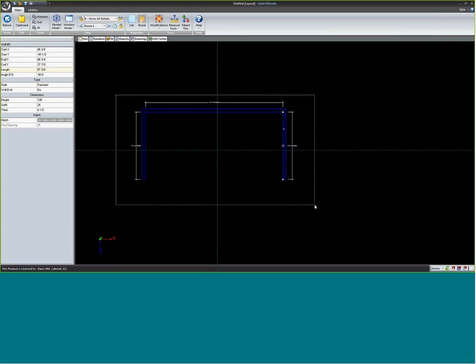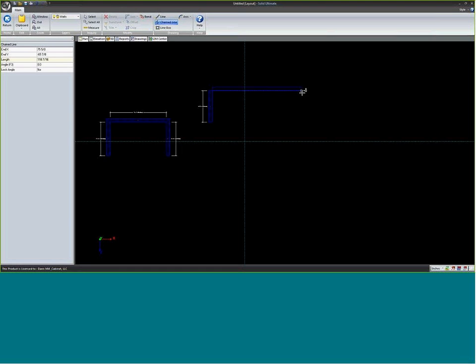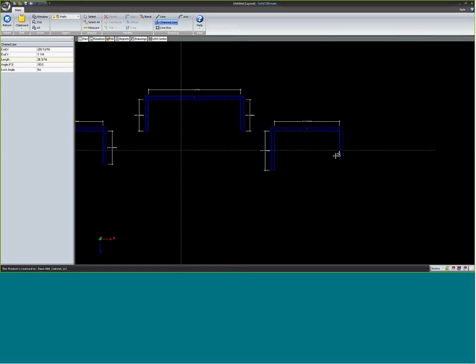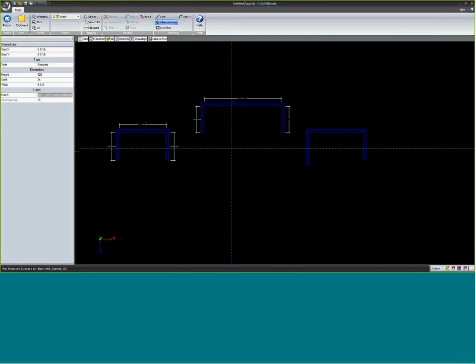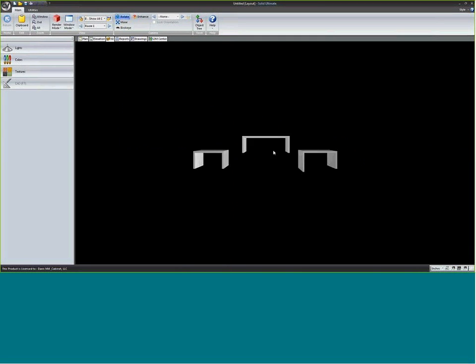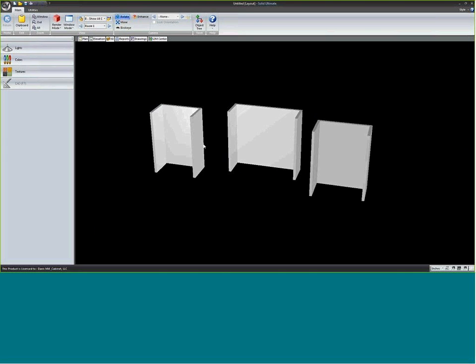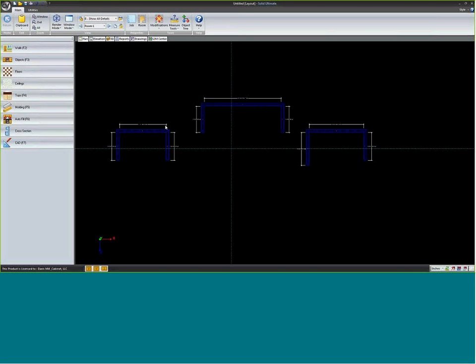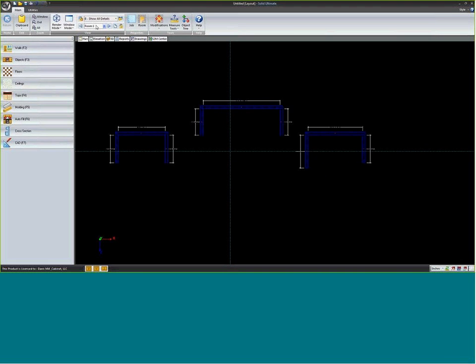Another thing that's pretty common for people to try to do in Cabinet Vision is combine rooms together. For instance, if I have 2 or 3 bathrooms that all have the same door style and finish and everything else, I might draw walls something like this. Okay to do. It gets a little bit hard if you ever want to see a 3D image of it, because you're going to see these 3 rooms. But it's also more difficult to keep your rooms straight. So I would always recommend treating that as one room, that as one room, and that as another room, not to combine them together.